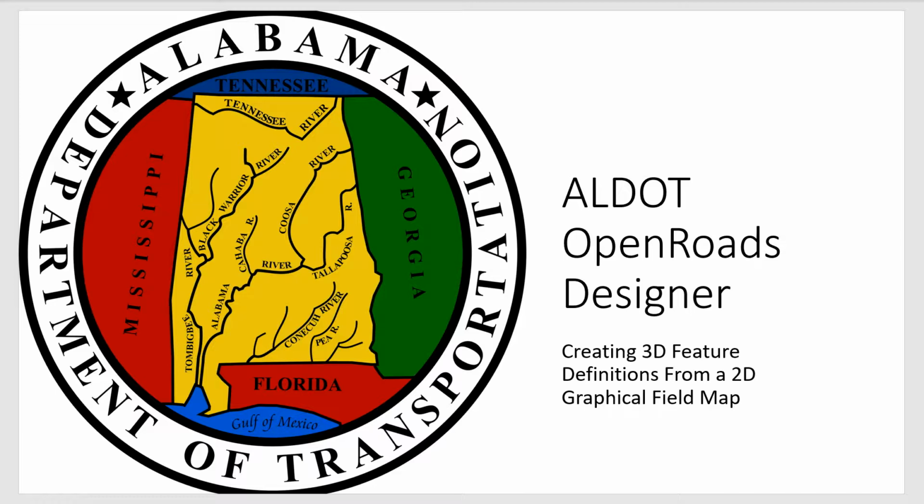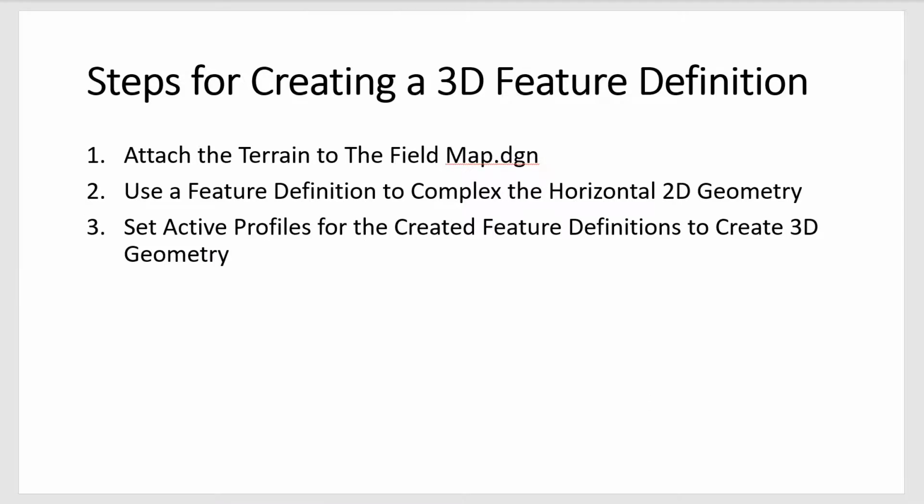In this video, I will demonstrate how to create 3D feature definitions from a 2D graphical field map. The steps for creating a 3D feature definition are: 1. Attach the terrain to the field map DGN and set it active. 2. Use a feature definition to complex the horizontal 2D geometry. 3. Set active profiles for the created feature definitions to create 3D geometry.